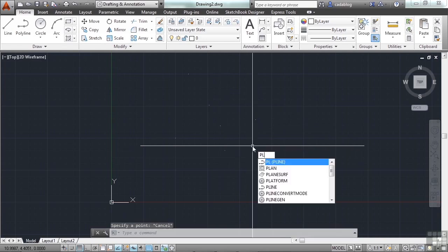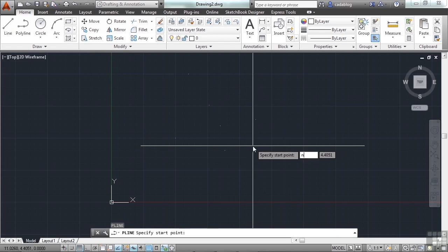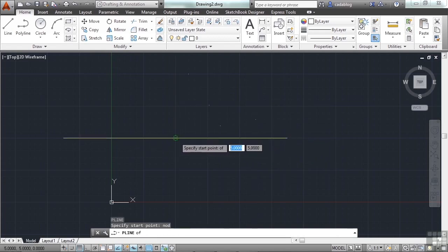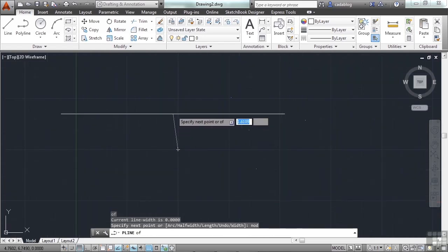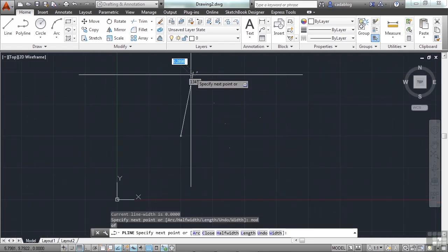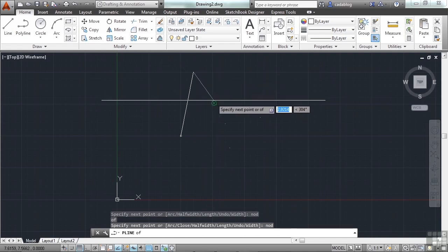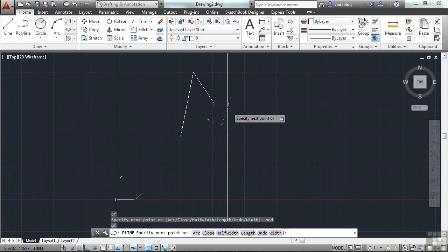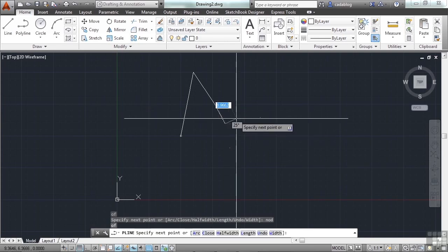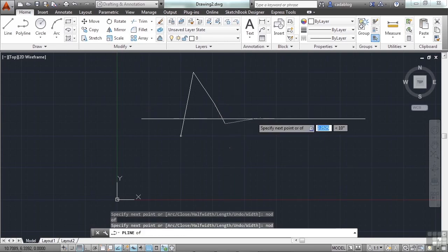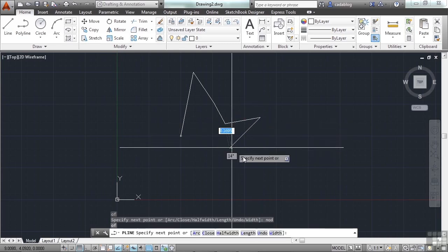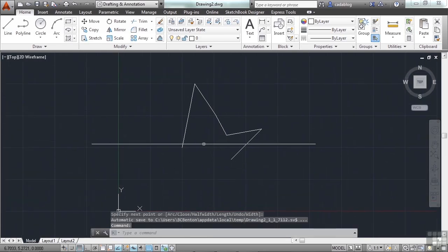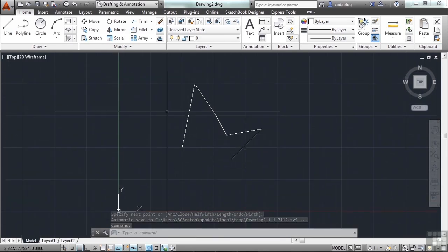Now start the polyline command and type in NOD for your OSNAP, which will be a node point, and click on one of the dots. And keep doing that and just connect your dots together. What you're doing now is just plotting out these points and then connecting them by drawing them together with a polyline. And you can make various shapes, etc. Now your points are still there. They didn't go away. They're just hard to see right now.